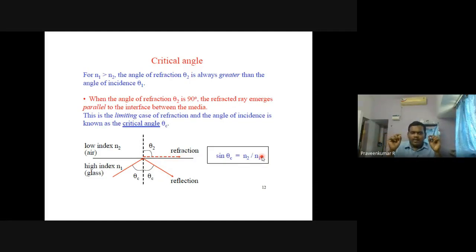If you are not satisfying theta c, the signal will not travel in the core. Maybe the signal travels into the cladding. So that is the loss. One more important thing I have to emphasize: theta c is important. If you are not dealing with theta c properly, the signal is lost. So that is the idea behind the critical angle.